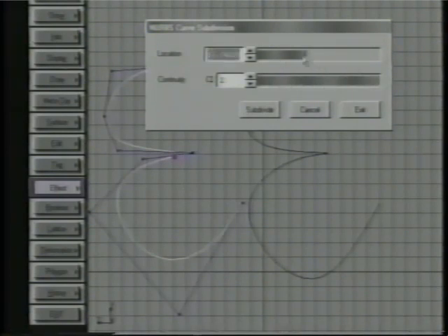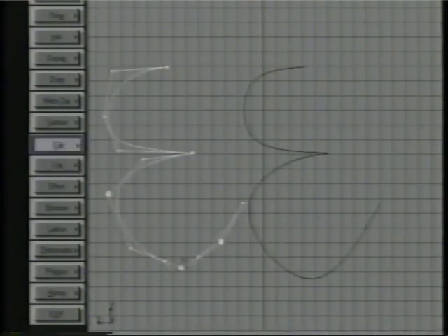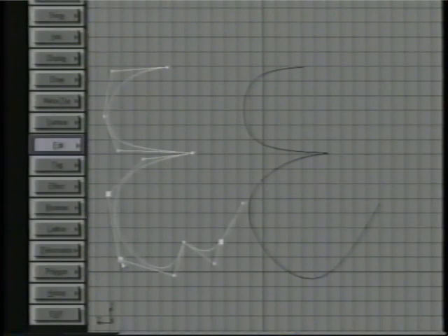So let's first add a cubic point. We can add that wherever along the curve, and when we subdivide, it doesn't change the curve at all. So that's very useful. And then I'm going to add a hard edge curve over here, and you can see how that acts. Subdivide. So right here, we untag those. Right here, this is a hard edge, and we added a point here, and it didn't change the curve at all.